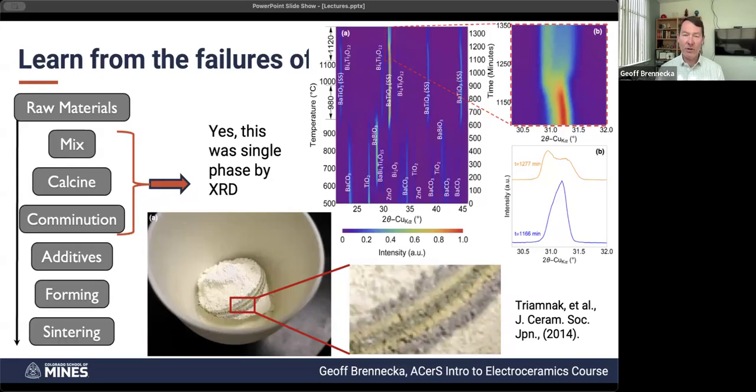When we did chemical analysis, we couldn't see any differences. What the heck is going on in this? But you can tell optically. And remember, optical properties can be really, really sensitive. Optically, there's obviously some segregation happening here. And so we ended up doing in situ diffraction along the way and noticed that we were, strangely enough, forming this weird barium bismuth oxide intermediate phase where the bismuth is half 3+ and half 5+, just completely unexpected.